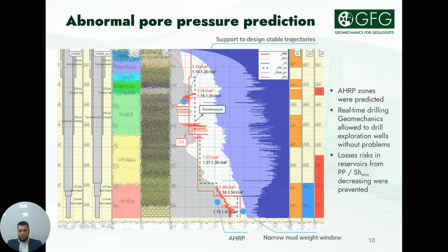On the other hand, the excessive increase of mud weight can lead to losses because, as we can see from this figure, the safe mud weight window narrows significantly. This is confirmed in some other wells in which, after a certain distance, we see a step-by-step change in increased gas readings and losses.